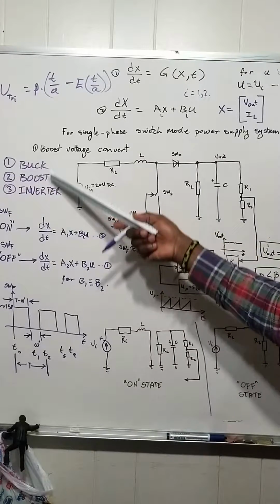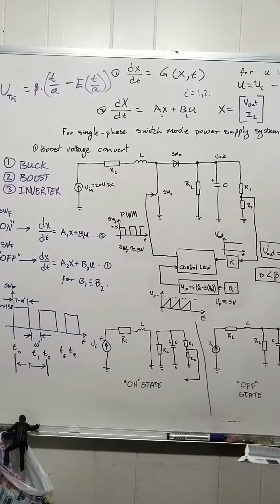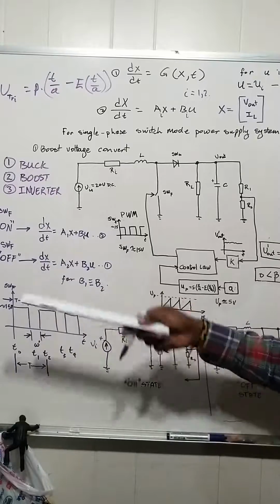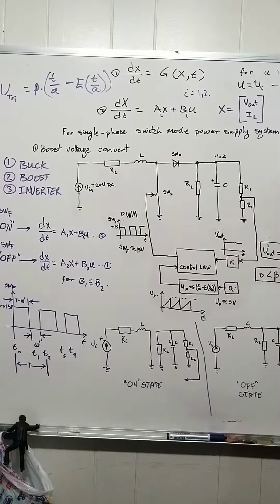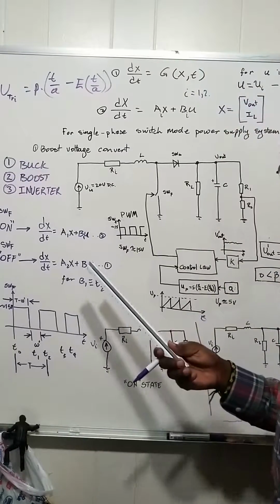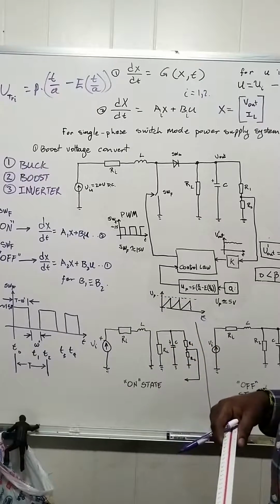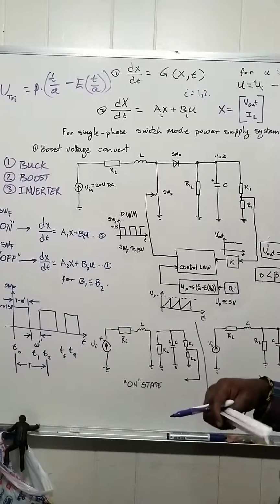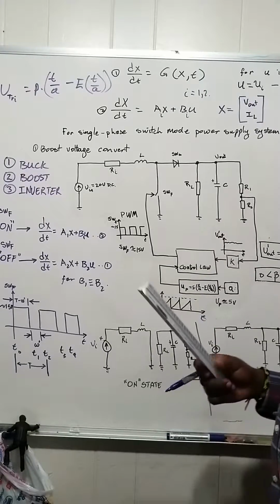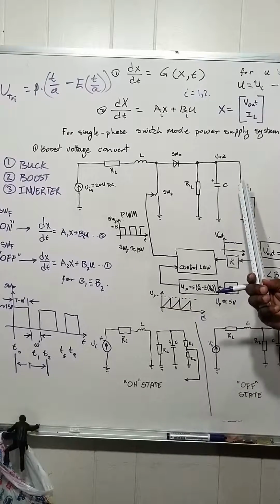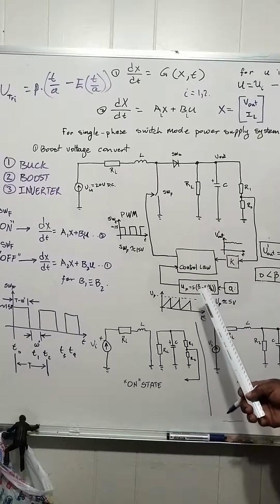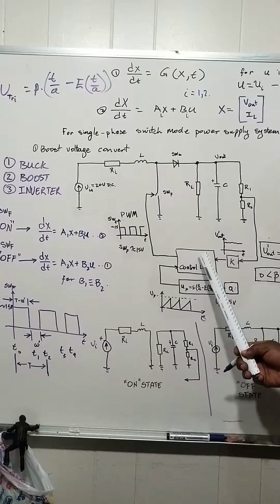All of these converters carry out what we call states. They can be the on state or the off state, or a state in the discontinuous system. What I'll be doing is strictly the continuous conduction mode system, and when I go to the discontinuous, I will show you another thing. What we're looking at here is the circuit itself, the arrangement, the feedback control, how it's arranged, the control law, what is inside here.